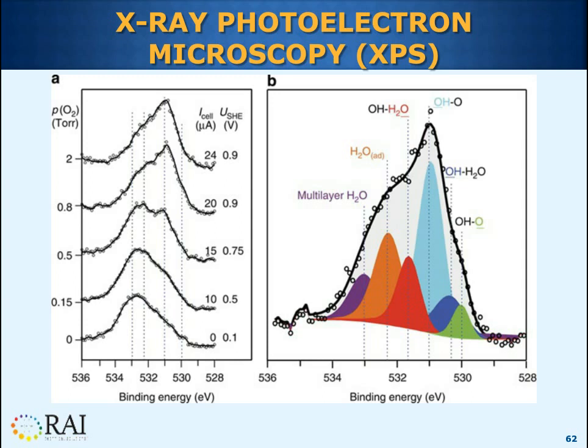compound. The XPS spectra that I'm showing in this slide is an example of various moisture components on a sample surface. The technique works by measuring the binding energy of a material. Using this information, the binding energy, I can determine in this particular case if a contamination of a surface prevented good paint adhesion, and if so, the specific composition of the particular contamination.